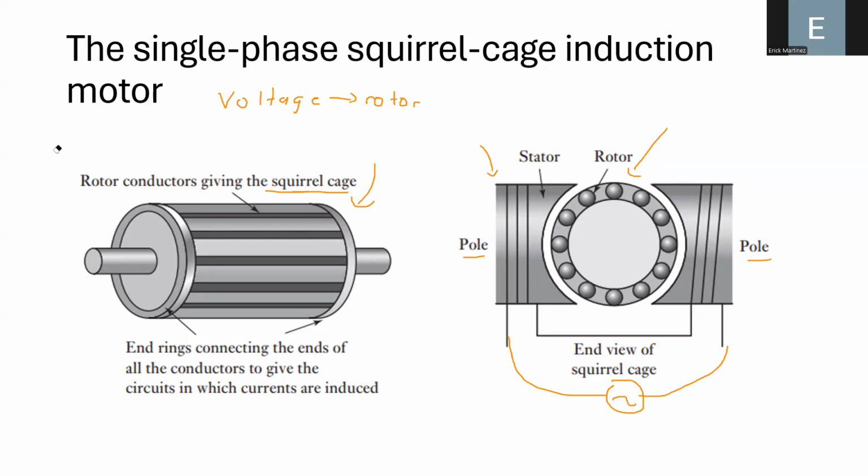So that is the main consideration of an induction motor: we are producing a rotative magnetic field in the stator with the purpose of inducing a voltage in the rotor that consequently allows us to produce a torque, which helps the machine to start turning or spinning.